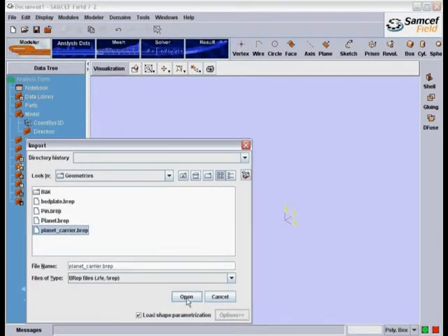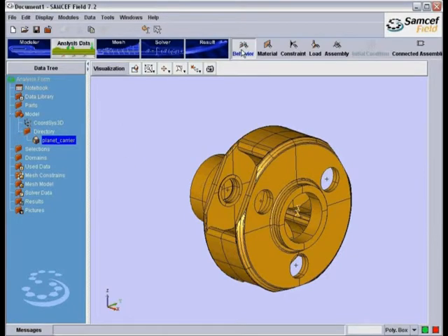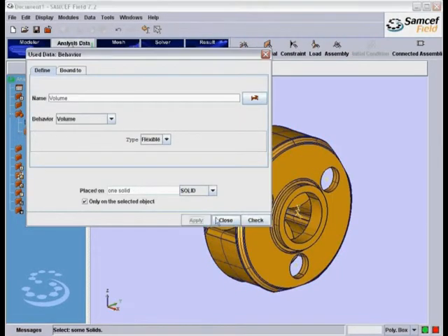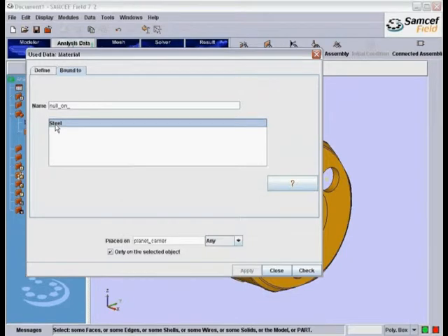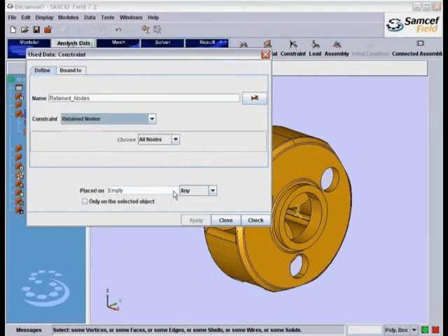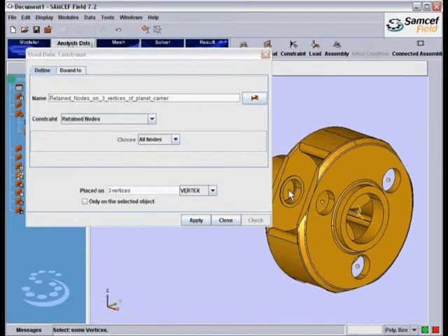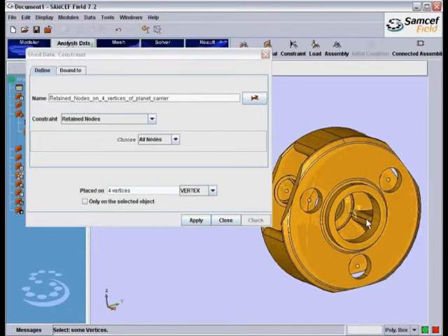First, import the CAD geometry. Then, assign the needed data. In our case, the behavior and the material data are enough. The material can be imported directly from the library. The data related to superelements should then be defined. These are called retained nodes and will eventually define the degrees of freedom that still exist after reduction. The retained nodes in our case should be the connections with the pins, the input and output shaft, and the planet carrier bearings.